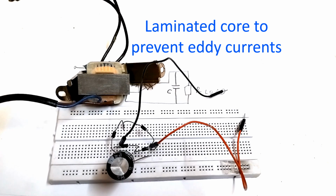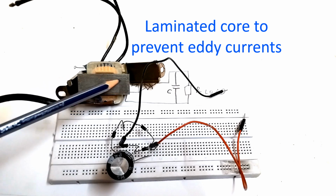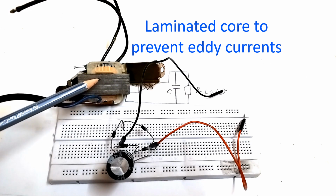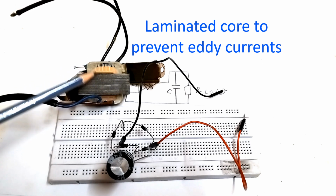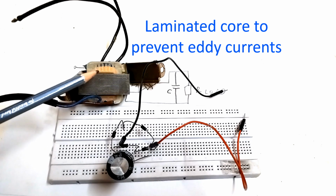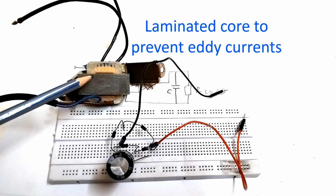I have just removed part of the cover of the transformer just to show the laminated core. You can see that this core is made of several laminated sheets, and the lamination is needed to prevent eddy currents. The core will have eddy currents, which will heat up the core, and that can be prevented by using a laminated core. When eddy currents are there, that will cause generation of heat and loss of energy, so the efficiency of the transformer in converting the power will be reduced if you use a core without lamination. A core with lamination will improve the efficiency of the transformer.